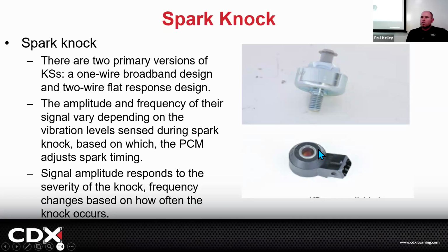So let's just say, you guys know if you have a high performance car, it calls for 91 octane, right? 91 octane because it's supercharged or turbocharged. You pick which one. Both. All 3: high compression, supercharged, and turbocharged, because America. We could do that. All right. That calls for 91 octane. But you know what? One day you're out of it, you forget, you pump 87. What do you think is going to happen? You're going to lose a lot of power.